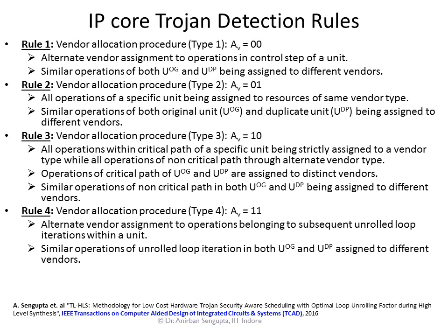This ensures that both copies don't produce the same output, because if one component or unit comprises a Trojan, it will produce a different output than the other. So in case of a difference, finally the comparator or voter indicates that there is a Trojan inside one of the units.